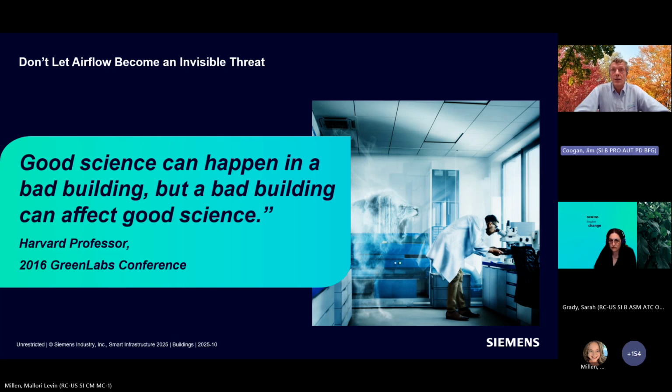Sometimes you can just put in new numbers. Sometimes you need some new parts. And sometimes you have to just adjust your calculations. I've had some jobs where a couple fume hoods might have been removed and they had a 14-inch VAV box supply, and the choice was essentially you can't go down as low as you wanted. So maybe you have a higher air change rate for that room, or you have to look at actually replacing the mechanical equipment in that room.